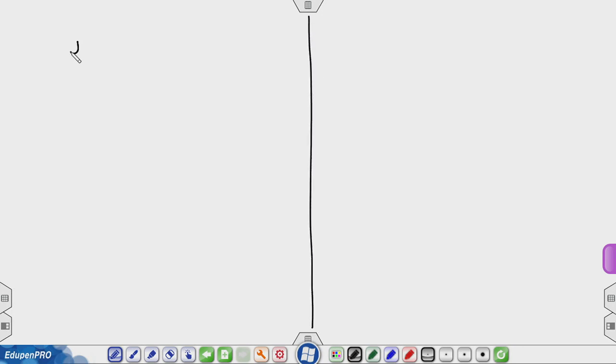The conductivity sigma is e n mu electrons plus e p mu p. Now, since this is an intrinsic semiconductor, if n goes up by 20%, so would p.